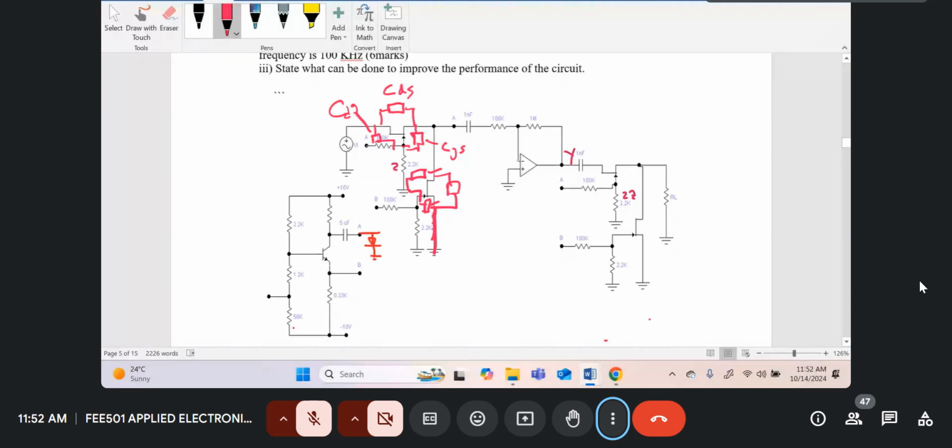But in the lab, I told you that because these capacitors are small, I've showed you some, the largest capacitance we are seeing is around 10 picofarads. And the reactance of 10 picofarads at the fundamental is approximately XC = 1/(2πfC) for the fundamental frequency. So if C is 10 picofarads, this is 10 times 10 to the minus 12 farads. So you'll find the reactance is quite small.